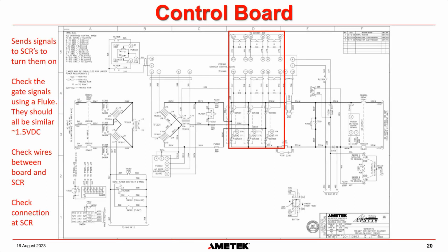We're just trying to isolate where it is. Is it at the control board, or is it at the SCR? Also, you need to check the wires between the control board and the SCR themselves. Maybe a wire has been cut or nicked or has come loose.